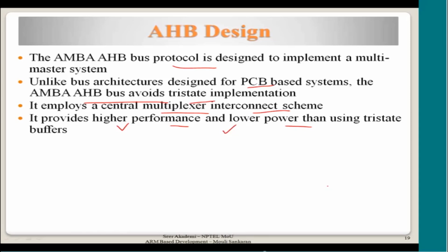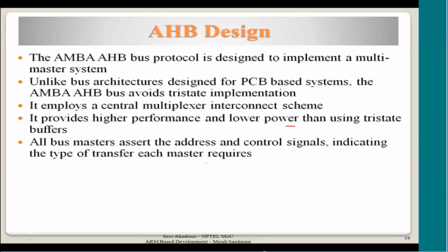Because if it is tri-state, every device needs to drive the bus, and it will take some time for charging the bus. Because of the capacitive effect, the time taken for the signals to stabilize on the bus will be longer in a typical tri-state system. Whereas if it is a mux-based system, everything is actually connected, but it is easier to achieve the proper performance, and it is lower power than using tri-state buffers.